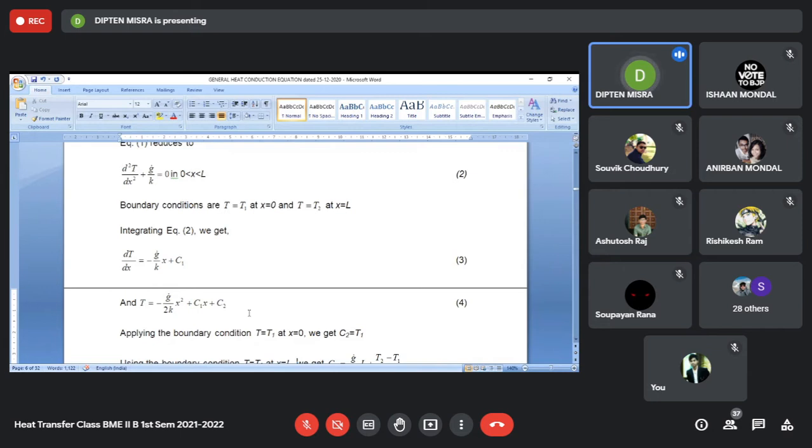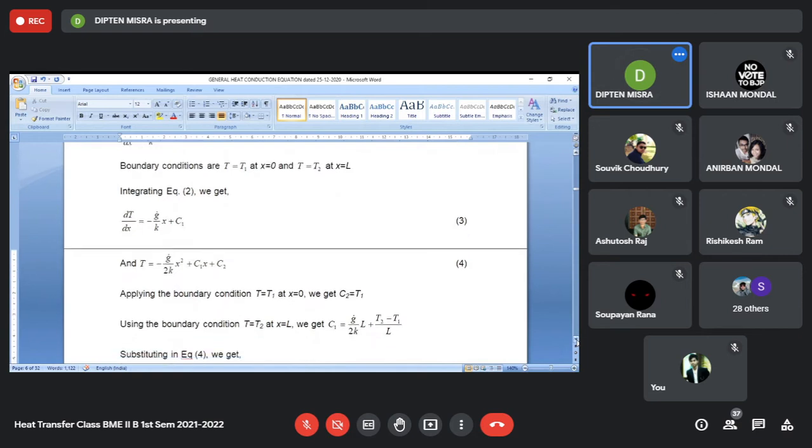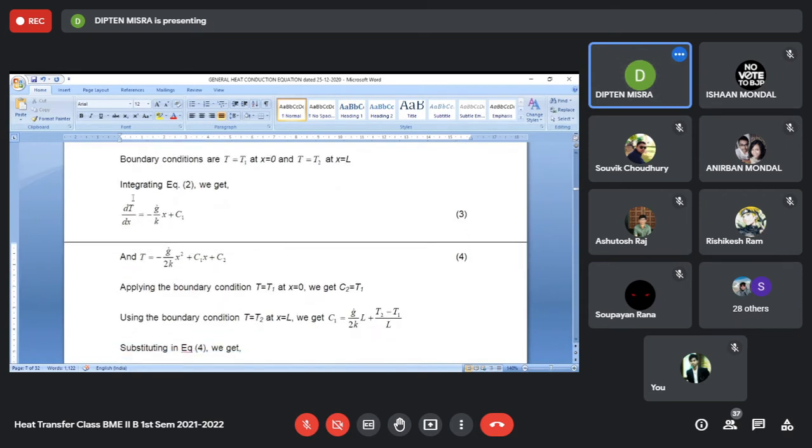That is why most heat transfer problems deal with the nature of variation of T along x, y, z. Then only we will be able to find out the heat flux and subsequently the heat transfer rate. Now, there are other things that we'll discuss about this solution. Another thing that we see is that in this case, the temperature gradient is a function of x.